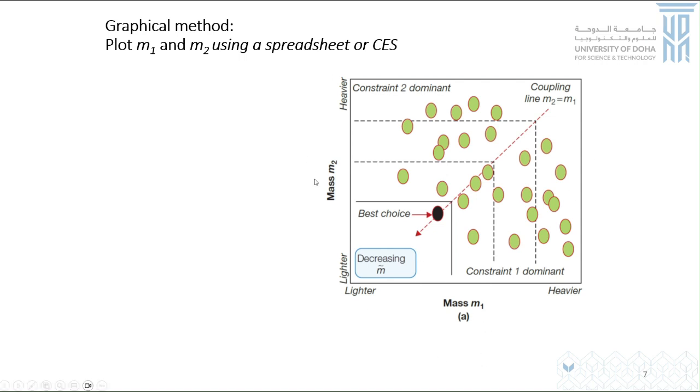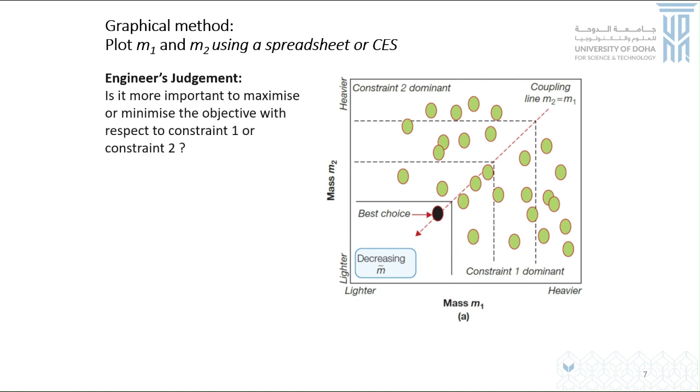But now the problem is, again, which material index is more important for you, because which performance equation is more important for you? Is it based on the stiffness or based on the strength? If you really don't care and you think both of them are equally important, then you are at the stage where M2 is equal to M1, isn't it?